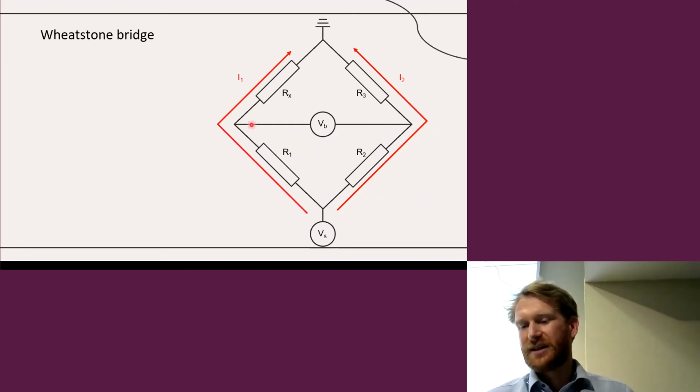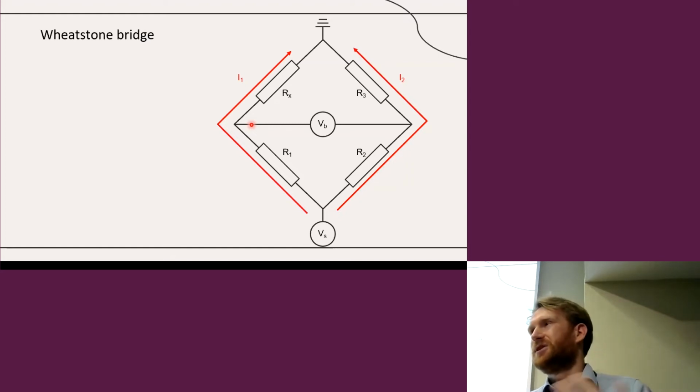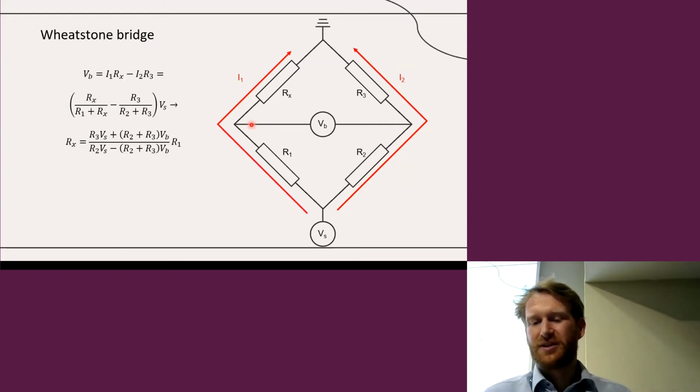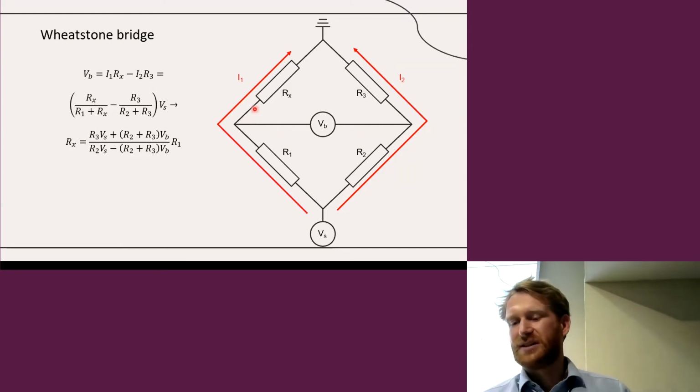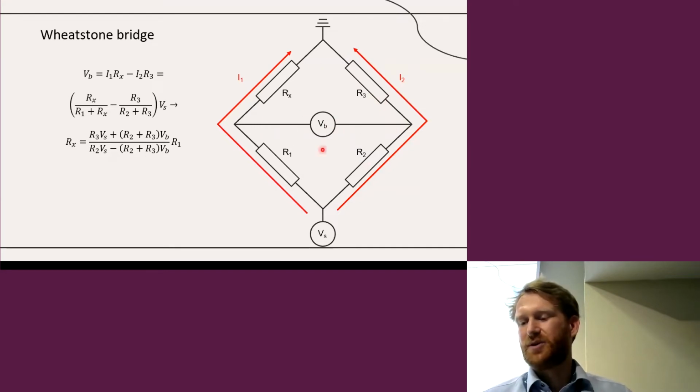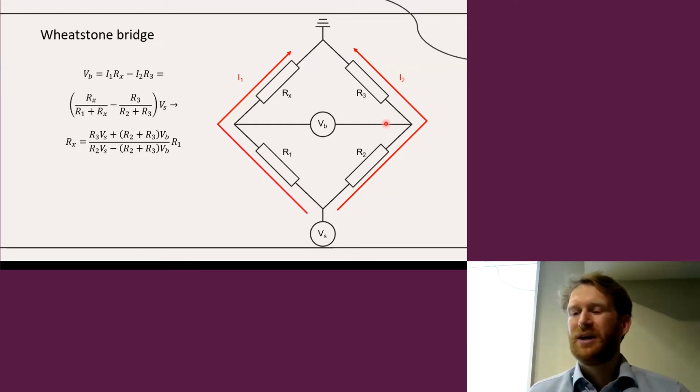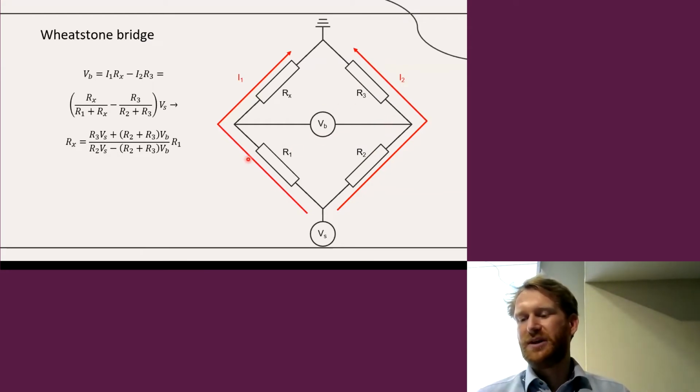Maybe a very technical detail, but for all the electronic measurements these days that people are doing, they generally use a Wheatstone bridge, because normally you measure the change of resistance. You have a very large absolute resistance, which can be kilo ohms, and on top of that you want to measure a change of a few ohms, which can be technically challenging. The Wheatstone bridge is a trick using a set of resistances where, if the bridge is balanced, if this is perfectly symmetric and all the resistances are the same, then there is no voltage between these two legs.